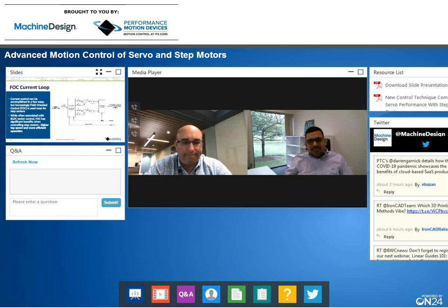Yeah, and actually, it's very interesting. You can actually hear it. You can hear the difference when it's turned on versus off in the line. Well, you can also hear when you set up your D and Q wrong. It sounds really bad. Yeah. So just having FOC by itself doesn't fix anything. You've got to have the FOC and you've got to have your D and Q terms in the right place. Otherwise, it sounds really bad.